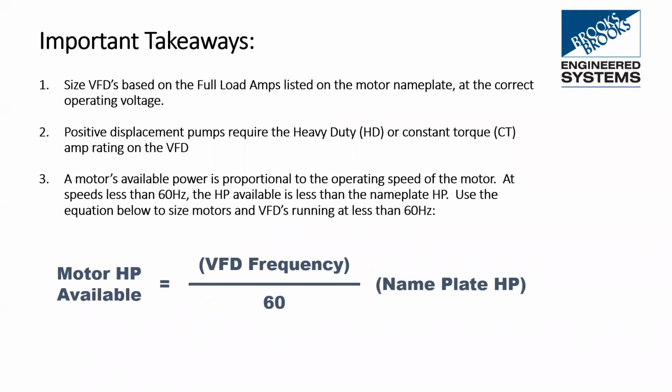Some takeaways here. Okay, so number one, just the basic sizing criteria: VFDs are sized based on amps and voltage. Number two, we have to make sure that when we're using positive displacement pumps, we go with the heavy duty or constant torque amp rating on the VFD.